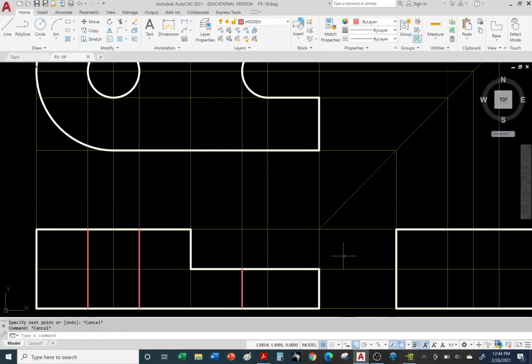Okay, and hit escape. For the other one, it's a complete circle, so we need a set of hidden lines to represent the circular hole. Okay, so here it goes all the way through, right? And there's my red hidden line. Or I shouldn't say it goes all the way through. This is where it stops. So this is the depth, and that's where we position our red hidden line.